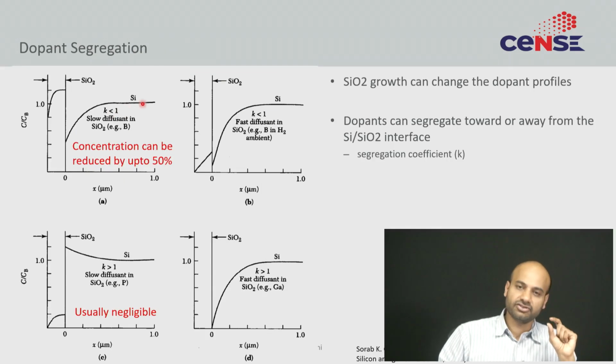Another advanced concept that is worth thinking about is the issue of dopant segregation. If you would naively think about silicon dioxide growth in silicon, you would expect that the dopant in the silicon would maintain its concentration in silicon dioxide when you oxidize the surface. However, practically this does not happen or is not as simple. The details are a little complicated.